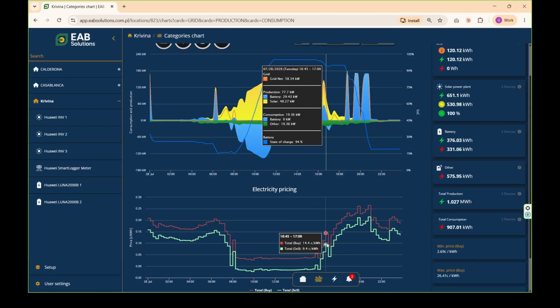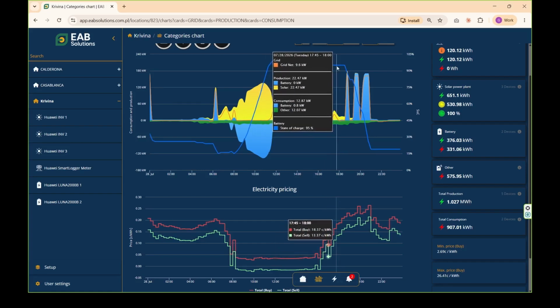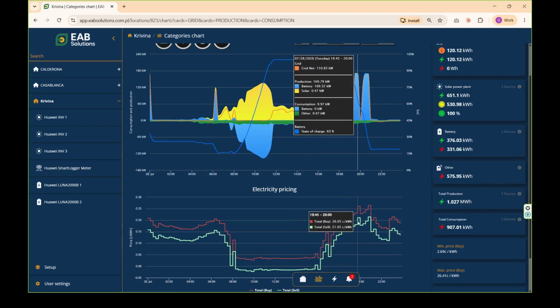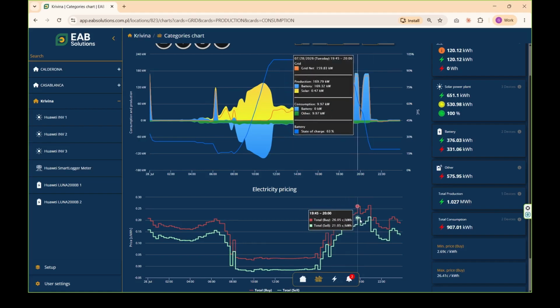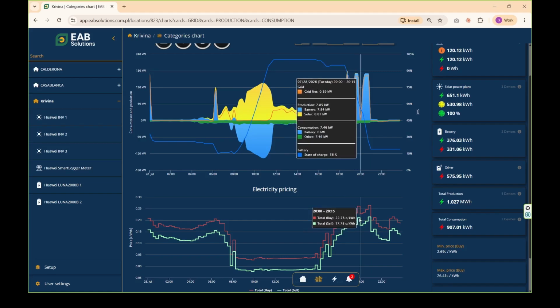Here we have the rest of the prices. Because prices are published the day before, we have the prices for the following day, so we know exactly what schedule to run. Our EMS knows what schedule to run, and at what time it makes sense to sell the electricity. What's it doing here? Exactly that. The battery keeps waiting, flat, until the moment of highest price. Here we see there are 3 peaks. This step, and this step are the 3 highest. And on those 3 peaks are battery discharges. Here, here, and here.